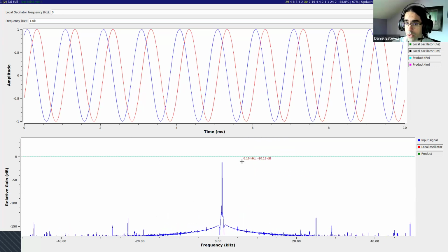And this is because for complex signals, it makes complete sense to speak about positive and negative frequencies as different things which are tangible because of this I leads Q versus Q leads I thing. And so the FFT can discern between negative and positive frequencies. It is able to show us just the positive frequency when we give it such a complex cosine function of 1 kilohertz.